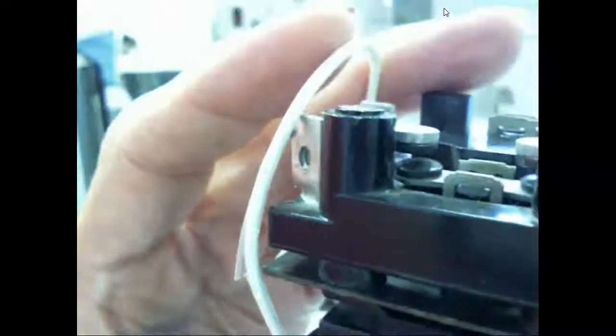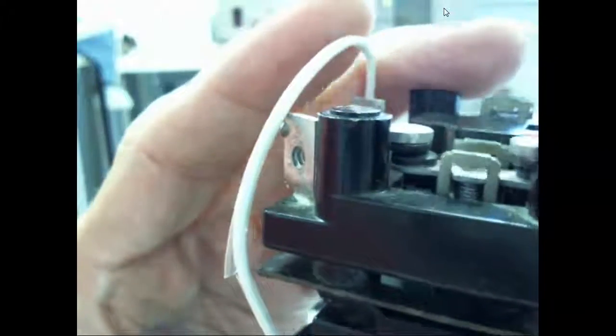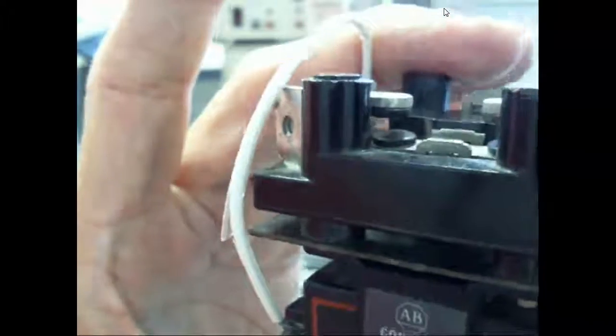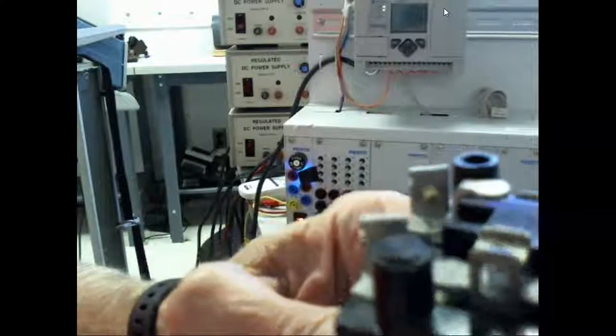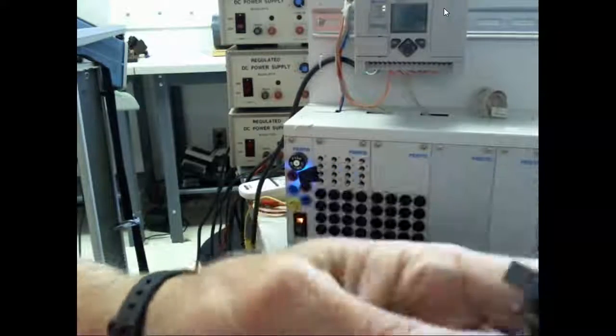Right now this one's open. Notice now it's closed. You can actually see the spring under it. And this right here on this side is already closed. So these are normally closed, and then when I actuate, they're going to break. Now these are double break contacts. This is the armature. Some people call it a plunger, and this is a relay.